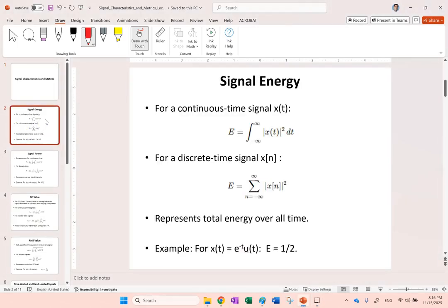If the signal is continuous, and I mentioned it in one of my previous videos, if you square the signal and integrate it over all time, that is going to be the energy of the signal. And using Parseval's theorem, you can also integrate it over all frequencies. So if you get the X of f and square it, so there is no negative part to cancel positive parts, and integrate it over the whole range of frequencies, that will also give you the energy of the signal.